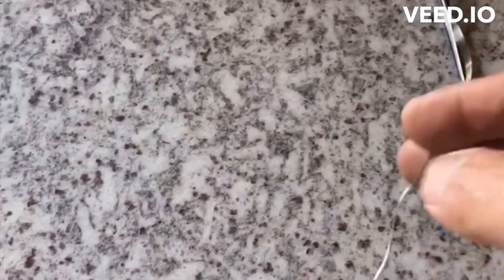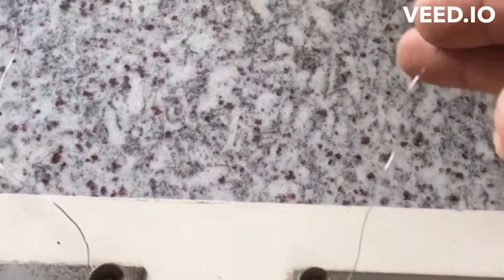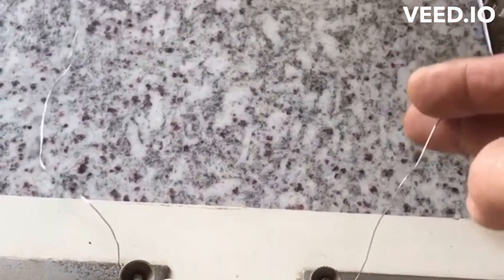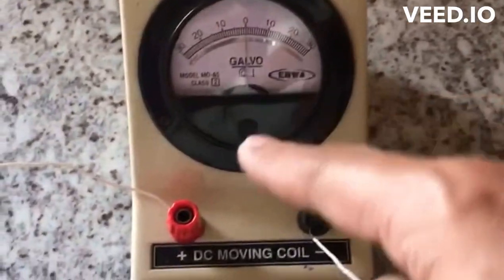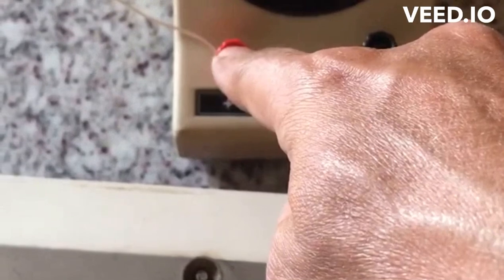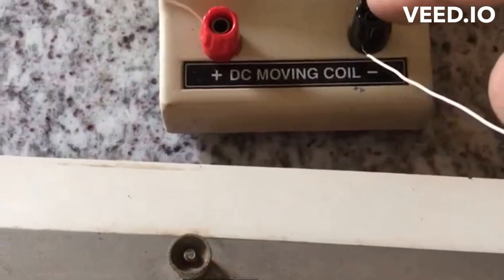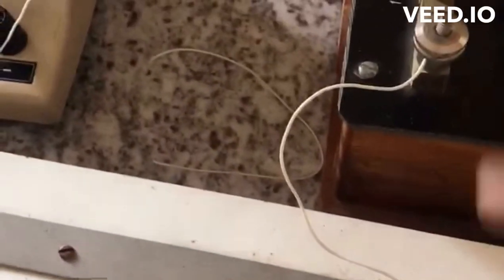Now let's look at the actual connections. This is the wire whose resistance is to be found out, and hence the specific resistance of the wire. This is the galvanometer. The positive end is connected to the middle terminal and the negative end has gone to the jockey. Whenever you make the connection, please take a long enough wire for the jockey because it has to move from this end to the other end. Take 2 short wires for the resistance boxes because they are at shorter distances.